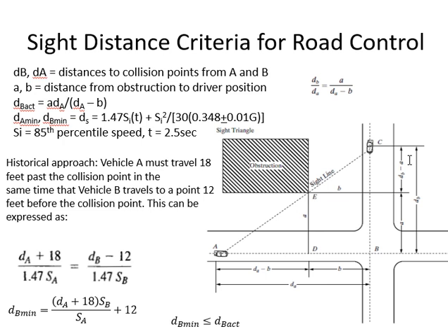Okay, and a very important criterion for the intersection is the side distance. Since you are looking at the car coming from the side, the side distance is obstructed by the obstruction on the side of the road. So it's not like you are looking ahead. And then we discussed two approaches. One is using the minimum distance equal to the side distance, and trying to see if the actual distance is equal to the minimum or not.